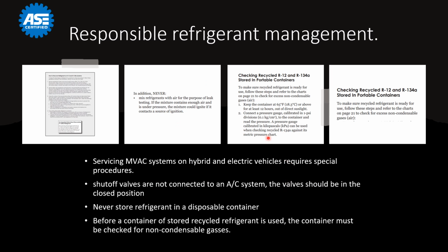So I'm just going to go over some of the things that I've seen and some of the stuff that I've noticed and some of the stuff that I think is very interesting, especially working on AC systems. The first thing that I noticed is if you're working on hybrid or electric vehicles, it's very important that you follow these special procedures that are in place to prevent you from getting hurt, because hybrid and electric vehicles have such a high voltage system that you need to know how to take the system apart, and before you even start working on the AC system, you need to make sure you disabled the high voltage system.